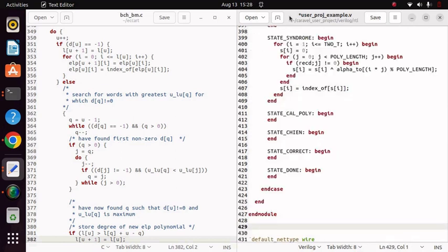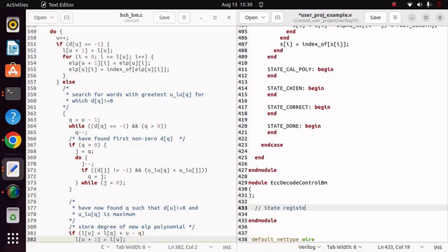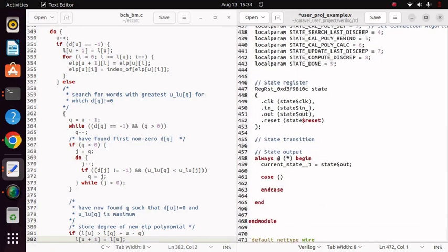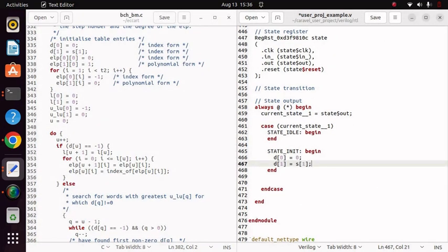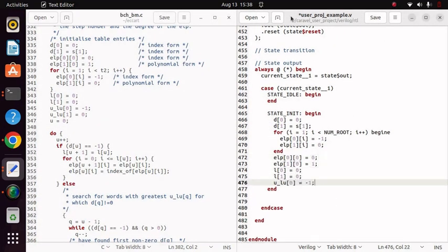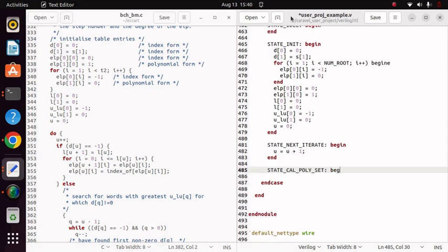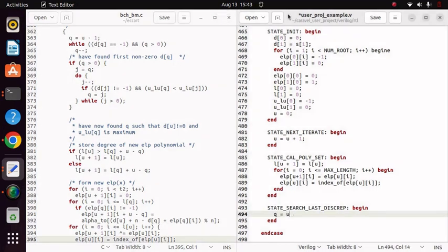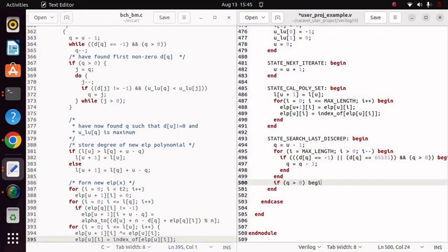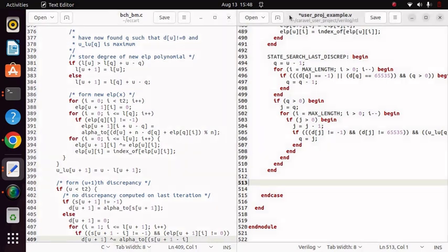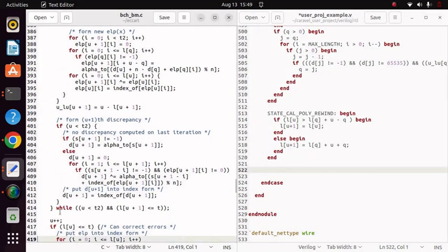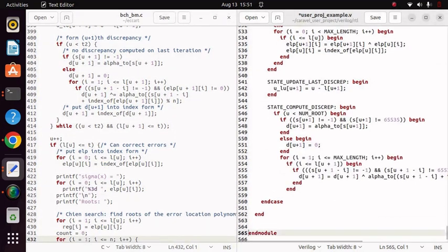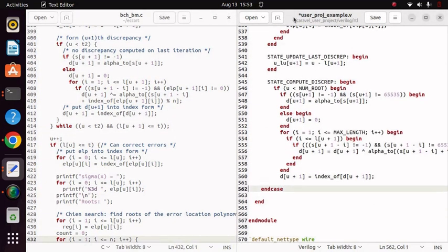The Berlekamp-Massey algorithm uses Girard identities to transform syndromes to the error location polynomial. The polynomial is constructed through iterations, reaching a state of zero discrepancy. If discrepancy is not zero, then go back to the previous good polynomial and add the discrepancy to it so that there's no more discrepancy, and continue. The algorithm would find a polynomial that results in discrepancy of 0 for all syndromes. Otherwise, it would declare the code is not correctable.